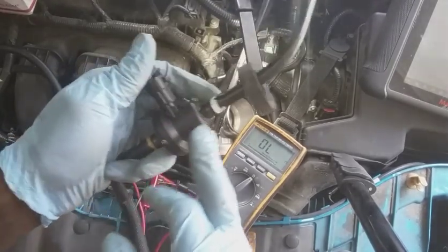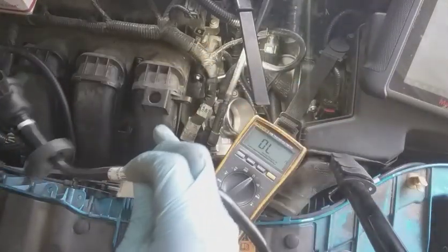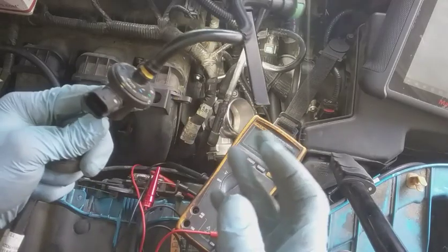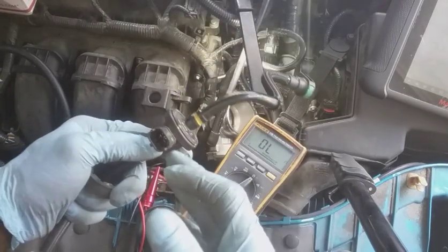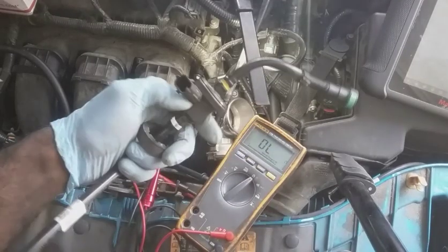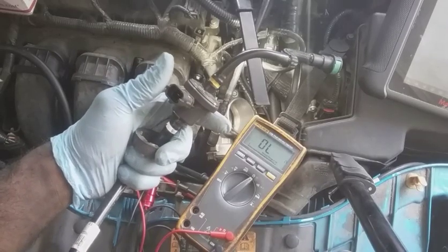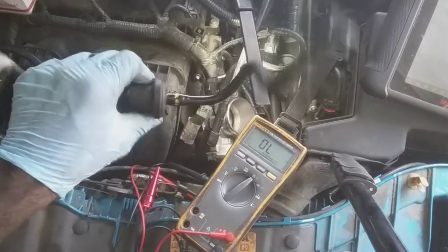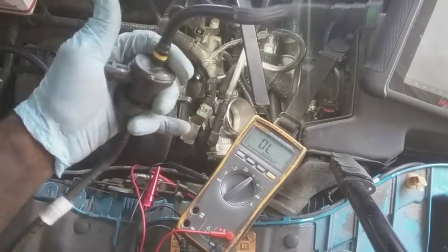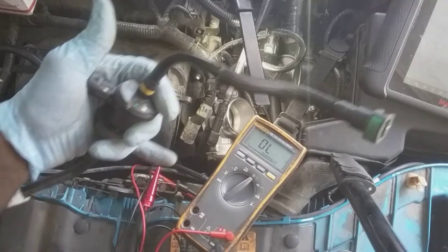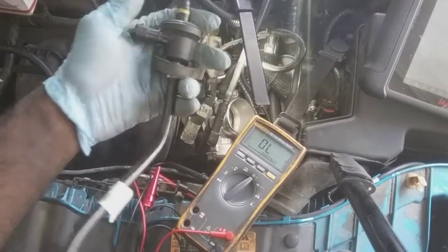More than likely, this solenoid at some point is just getting stuck open, and that's why when she put gas in the car it would stall, or while she's driving it would cut off. You saw what happened: even when we commanded this unit to 60%, it just stopped. It didn't want to work, so it just stayed open. So when she would slow down, it would create a vacuum leak or cause excessive fuel consumption through this evap system.